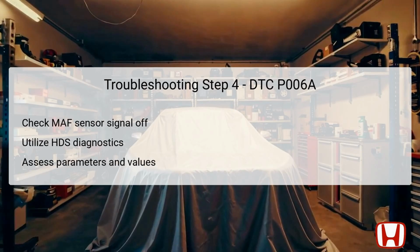For troubleshooting Step 4, begin by checking the MAF sensor signal without running the engine. First, turn the vehicle to the off mode and then switch to the on mode. Using the Honda Diagnostics System, HDS, measure the MAF sensor input at this stage. Aim for a parameter value of approximately 0.2 grams per second, g/s. This value serves as a threshold for determining normal operation.